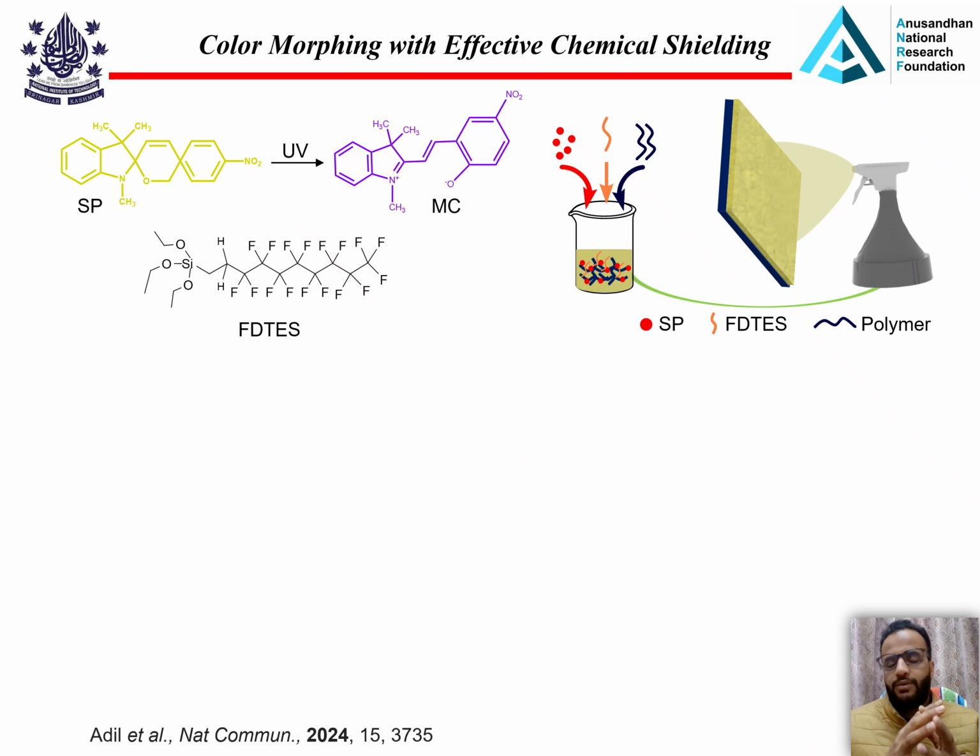So these surfaces can repel all liquids, whether it is an organic liquid or an aqueous liquid. In this project, we have designed super omniphobic surfaces, but most super omniphobic surfaces are unifunctional in nature, meaning they can only demonstrate oil repellent or water repellent or liquid repellent properties. If you incorporate any other functionality into that, it may compromise another liquid repellent property.